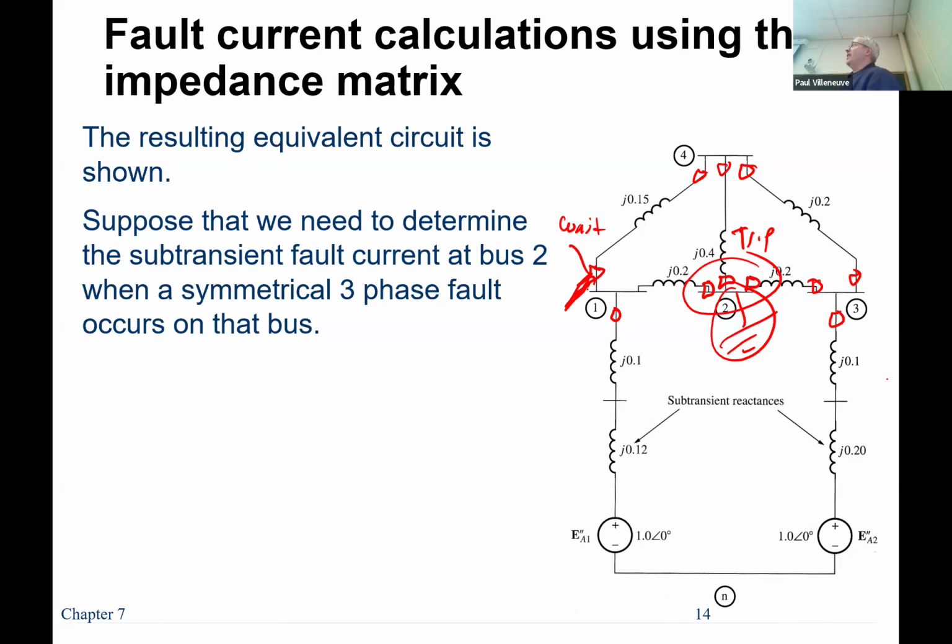And I had to think about it. And I'm like, all right, we'll try it. It's a fast differential. It should trip again. And it stayed in. But this plant was in Houston and I was in Maine at the time. And so the answer was somebody had left a ground screw in, and they had currents going where they shouldn't have gone.